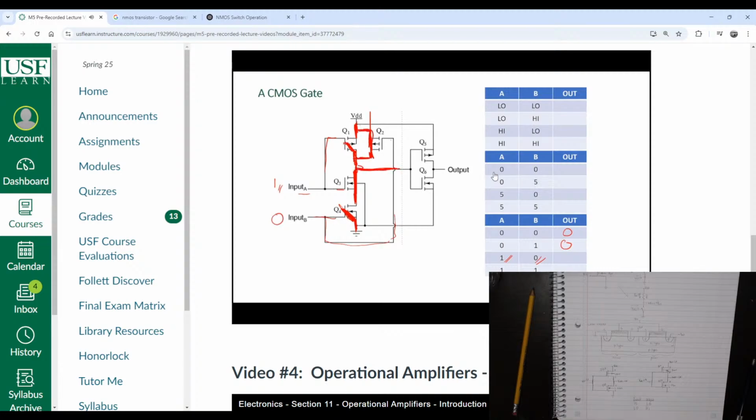And the point of interest again in the middle, notice that again this node here is connected via Q2 to VDD again. So this is high, therefore the output is low, another 0. We have one case left. Let me mark in all my zeros.